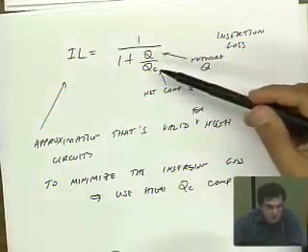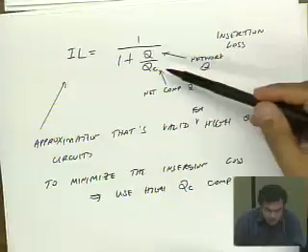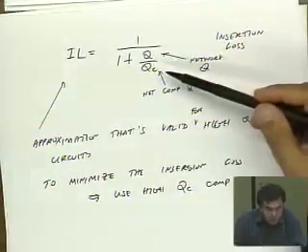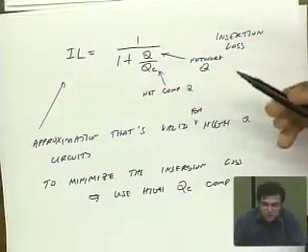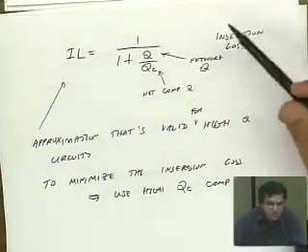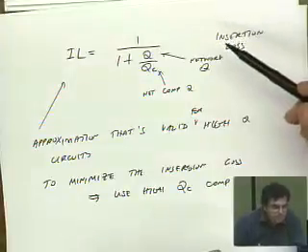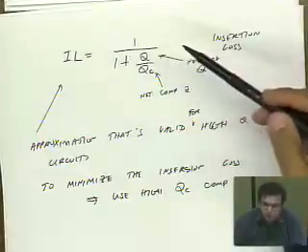It's not going to really matter that much. It's a marginal difference. On the other hand, if someone says that my network Q is 100 and I want to use components with a quality factor of 100, you can see right away that the insertion loss is going to be more than 50%. Right? So it really matters what network Q you're trying to achieve.